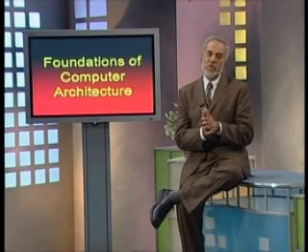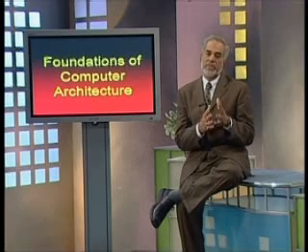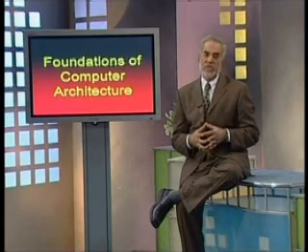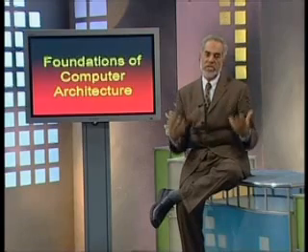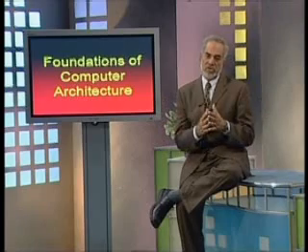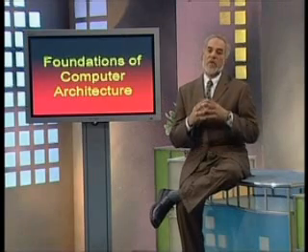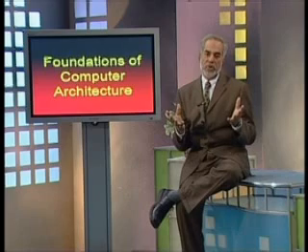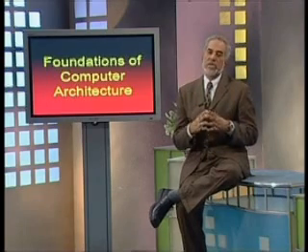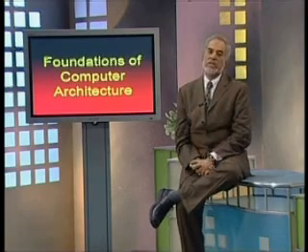So the assembler would automatically convert the program which is written in assembly of that particular processor. Therefore, when an architect defines the instructions, for each instruction he would define the opcode, and the rest of the instruction, different parts of the instruction, would tell where the different operands for that particular instruction are, and then we could store the result at some place. This information would be contained in the instructions.